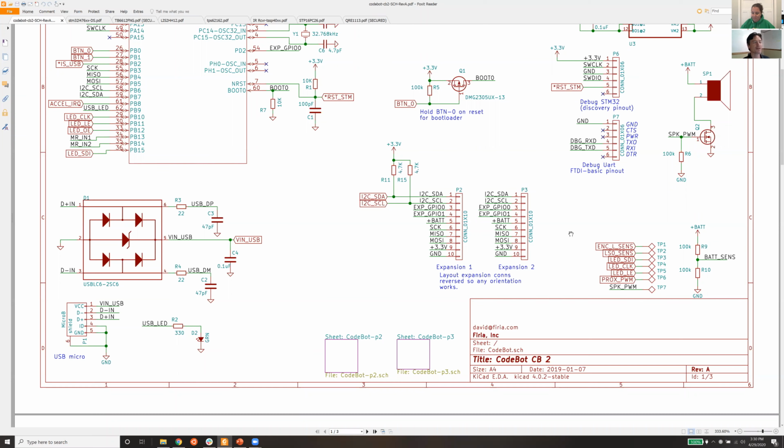Another super common way to connect things is called a SPI bus, a serial peripheral interface. And that bus is also brought out. That's this SCK, so it's clock, and then master in, slave out, master out, slave in. Obviously 3.3 volts regulated, which we'll see the power supply in a second, and ground are brought to the connector, as well as raw battery voltage, which obviously varies as the batteries are fresh and then go back to dead. But 3.3 is regulated. It's always going to be nice and solid. So that's really everything on the expansion connector.